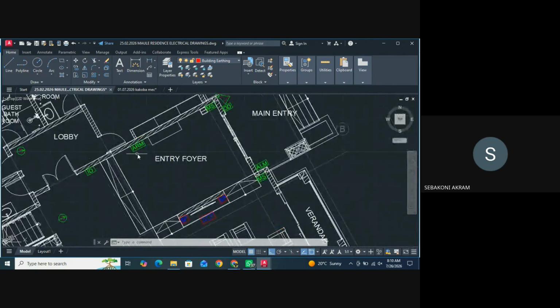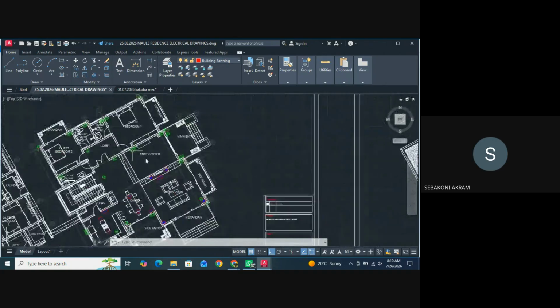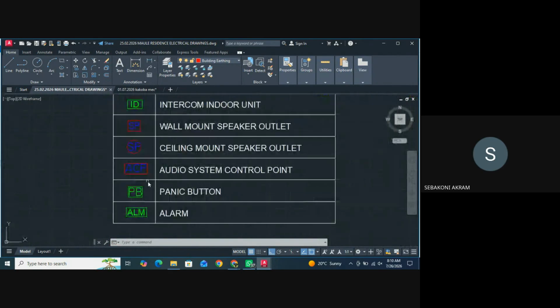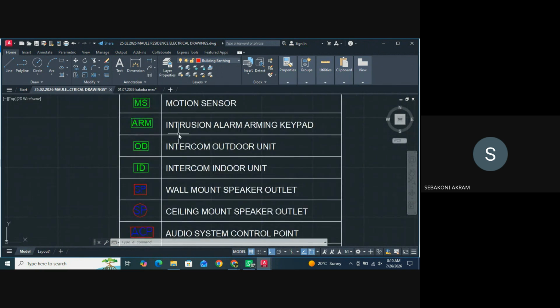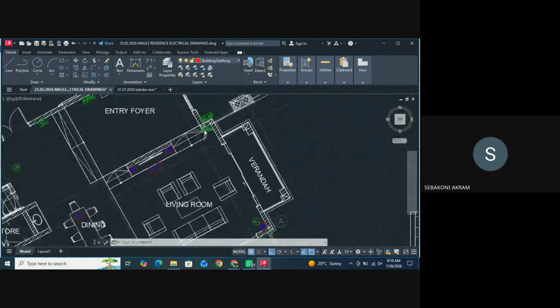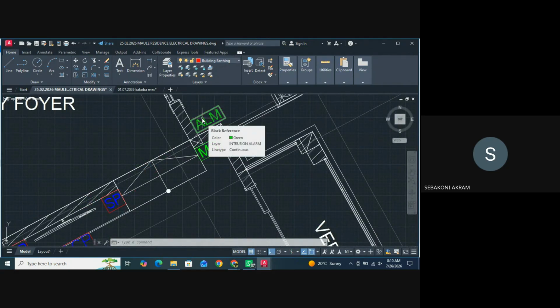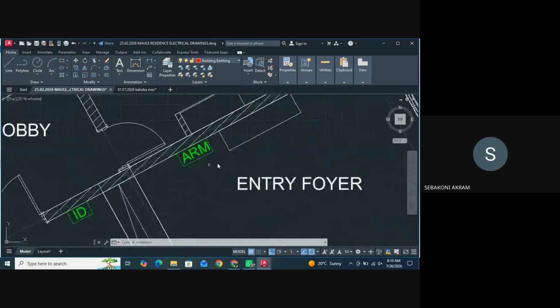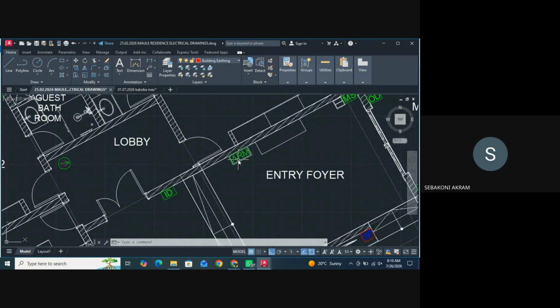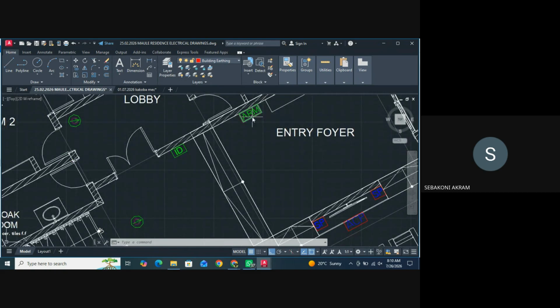Then this is our alarm control unit. This fire what? Yeah, sorry, the intrusion is inside. I did the right design. This is just an alarm outside. This alarm is okay being outside because it alerts neighbors. So this is what I told you. When you enter, the motion sensor detects you. So you come to the intrusion unit here, put in what? The code, before you continue. If you don't put in the code that you had set before, it is going to trigger the alarm.